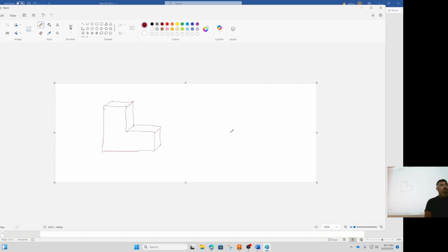Usually half. So with isometric, it's locked into one view, but with oblique, you can adjust which angle those lines are going based on what you want to see. If there's a hole up here, you can make it come more up. If there's a hole over here, we can make it come more down. As long as they're all the same angle and the same distance back, the same percentage, then we're good. So you have a little more freedom.